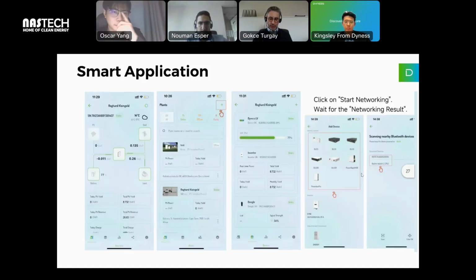Yeah, so that is the electrical thing, right? If you have a parallel connection, you keep the voltage the same, but the more batteries you add, the more the current goes up. Whereas when you connect the batteries in series, the ampere stays the same, but the voltage keeps on increasing as you add more batteries.